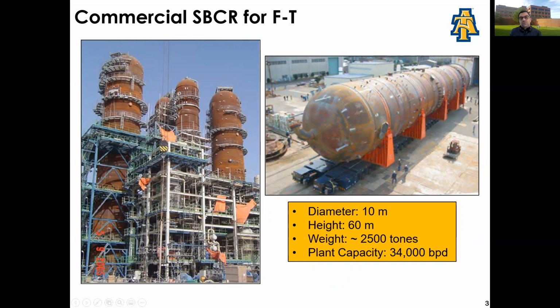In this sort of context, slurry bubble column reactors give you the advantage of having excellent heat removal, allows you to use very fine catalyst particles, gives you a higher yield per reactor volume. The pressure drop is lower. You also have the option of online catalyst addition and removal, and the construction cost is fairly low in comparison to a multitubular reactor, where my equipment is a lot more complex, right?